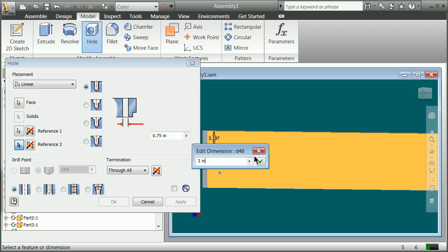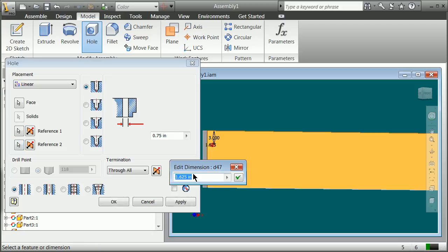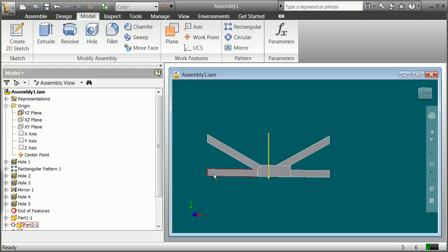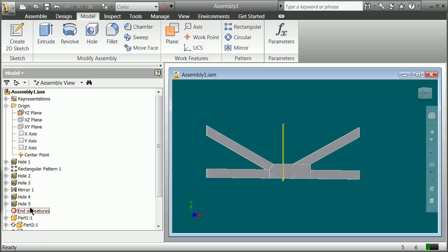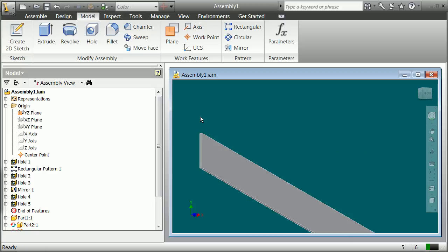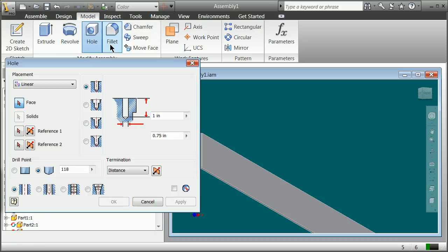and we're putting these in here just because it's nice to put those pin joints thoughtfully in the stress analysis, as opposed to necessarily just doing a fixed end. You know, just putting a pin joint on one side and a friction joint on the other. Hit there, through all, okay. So I'm going to finish the rest of these out. Let's see if we can get these 2 up and mirror it again. So let's see if we can get 2 more holes put in there and mirror the whole bit.